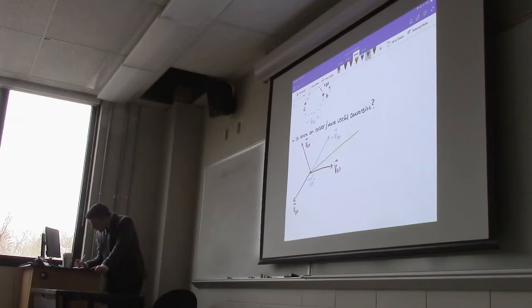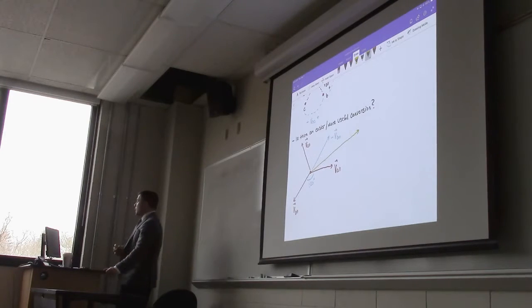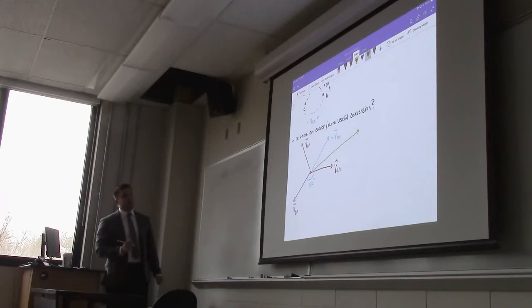It'll be a longer vector, right? Because we're going to be summing together the length of VAN and negative VBN. And the angle, right, is going to be in between the two. And so this right here is going to be a 30-degree angle. And this right here is our VAB.